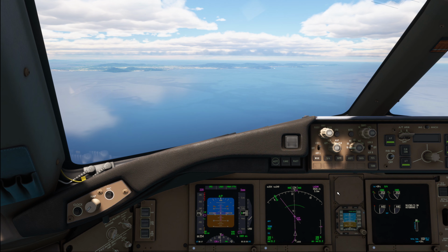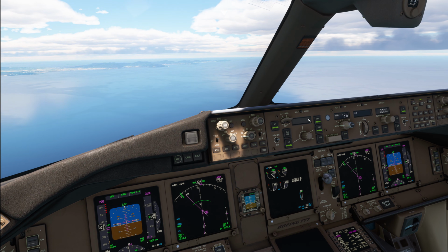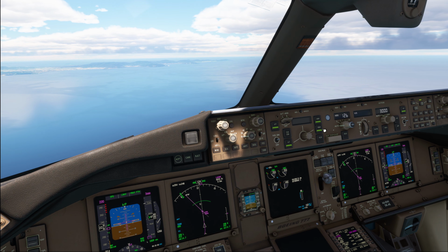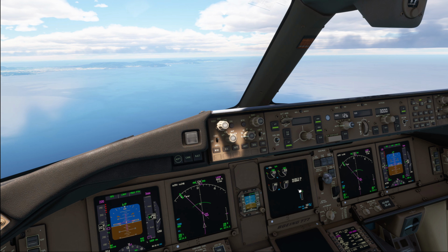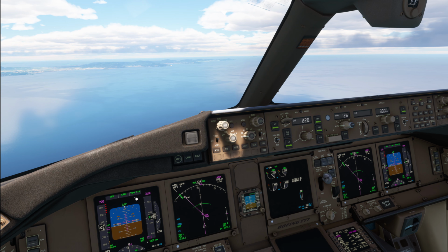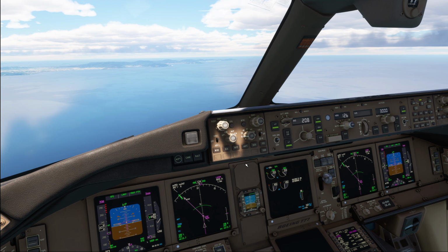Now, as we're approaching our final descent, remember 2 miles prior to the final descent, we are going to set our MCP altitude down to the minimum, verify or engage VNAV, and open up the speed window so that we have manual control of our airspeed. So just to show you, now that the flaps are out, if I open the speed window, you can see it remains in VNAV path, and does no longer revert to VNAV speed. So the on-approach logic of the FMC is now active.